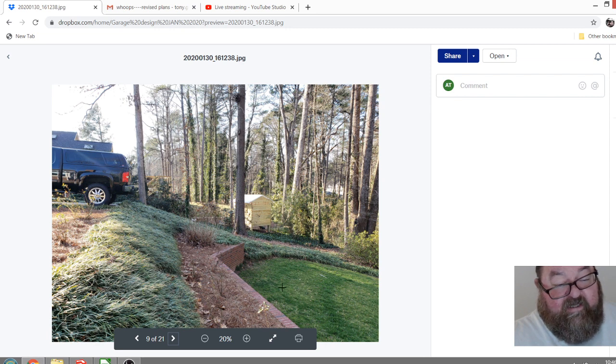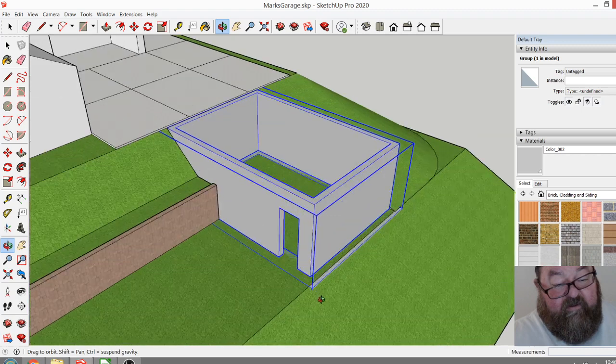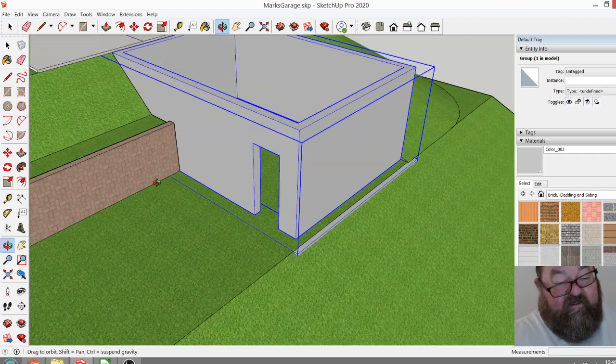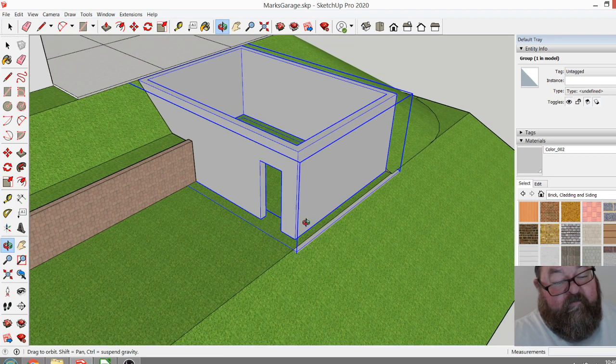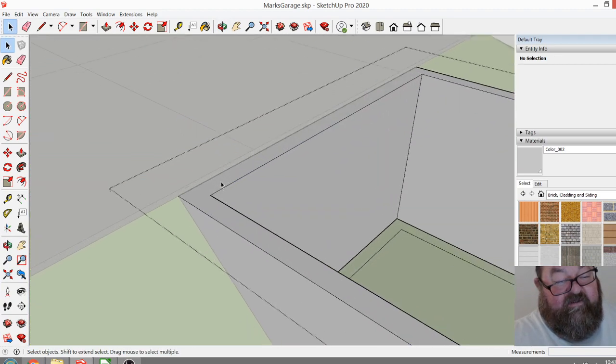But there's a question as to how tall these walls would have to be. They would have to be tall enough to go down here. When you come out the 26 feet, and I'll go back to here, you can see this flat spot is not this way. This is the way I would propose it be for at least an area. How to explain this? These walls have to go down to undisturbed earth so that your footings are on good soil. So this wall has to be tall enough to get down that far. So this wall may end up actually being 11 feet or so tall.